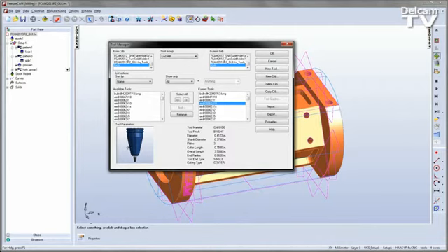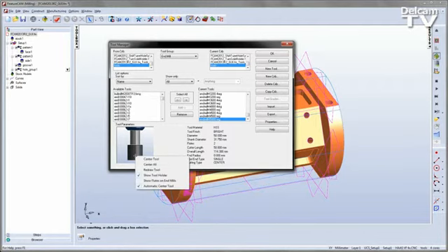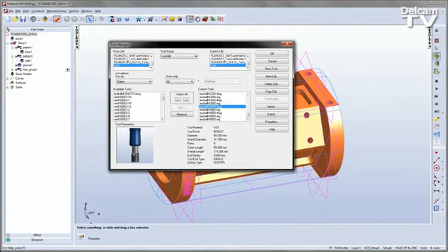If I hover over this area, you'll see that the tool will zoom in to where the cursor is to center on the cutting portion of the tool so I can see more detail. This happens for all the tools. If I wish to turn this option off, I can right click and I get a series of different options available to me. For example, I can turn off the automatic center tool, then when I hover over I no longer get the option. Again, that is reflected in all the other tools. Right click and I can turn that option back on again.